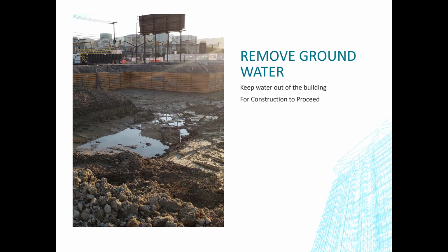But you can kind of see in this picture the clay, where the soil changes somewhere around right here. And once you get into the clays, usually you see some water being retained. The water doesn't move very quickly in the clay, but it does accumulate over time. So if we were to try and build something or do any footings, and I'll show you more photos here in a second, we need to dewater this area first for construction to proceed.